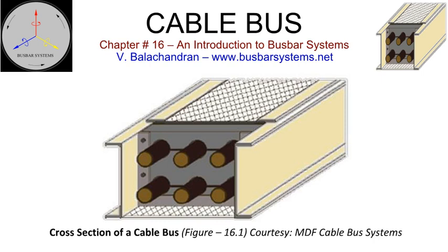Cable bus carries only those cables that are associated with a specific connection and is often mistakenly compared with cables running on cable trays. Cable trays are supporting and clamping devices for a wide range of cable connections that do not have a specified rating.